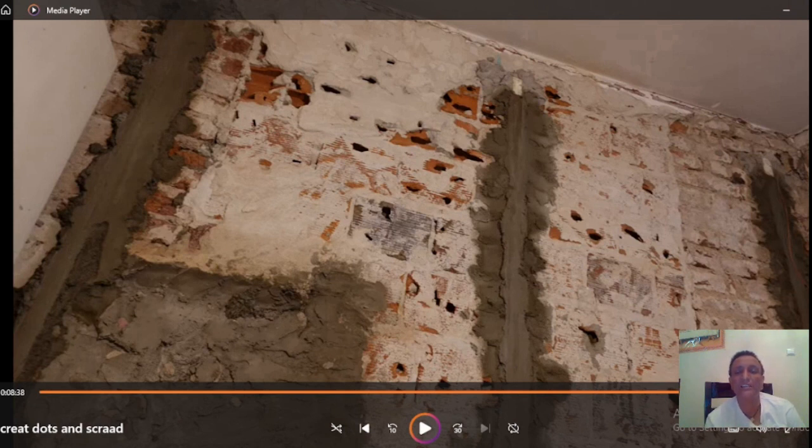Here, 3 screeds are created, so we can perform the plastering work easily. The only thing that we have to do is filling the mortar between the screeds. These screeds are used as a guidance or a reference line. In the next video, we will see performing plastering work by using these screeds as a guidance.